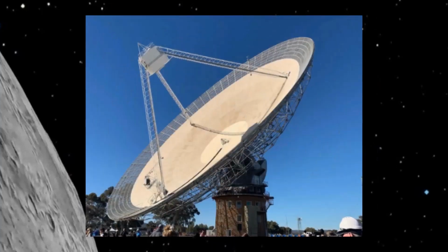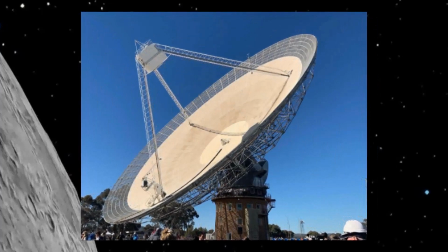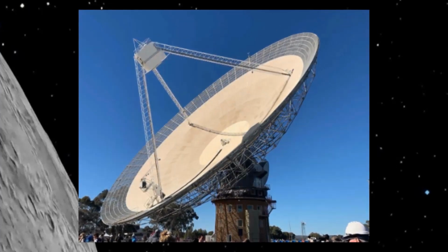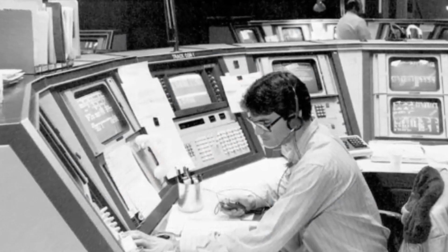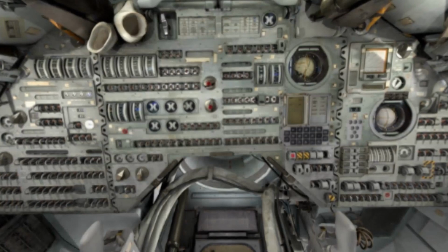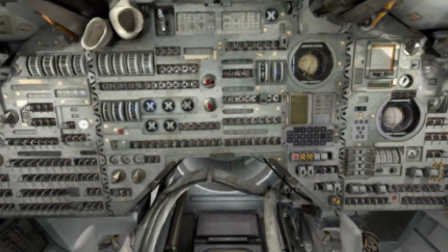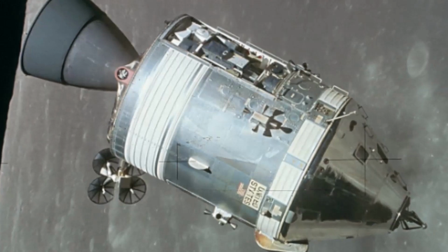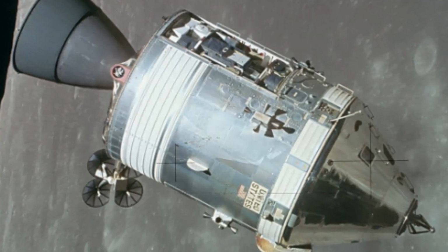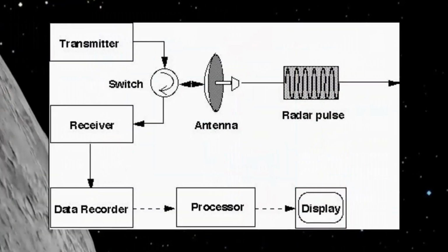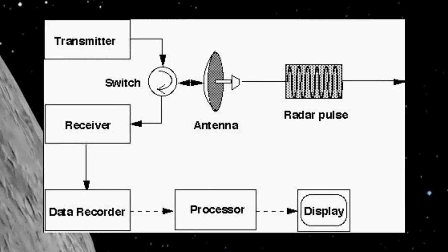Given that a powerful, accurate radio signal would in any case be sent to the spacecraft to carry voice and data from mission control, engineers simply arranged that it be modified on board in a known way and retransmitted back to the ground, this time carrying voice and data from the spacecraft. If the frequency of the signal from Earth was precisely known, then so was the spacecraft's, if it were not moving. After equipment on the ground received a downlink from the spacecraft, the precise frequency was compared to the uplink.